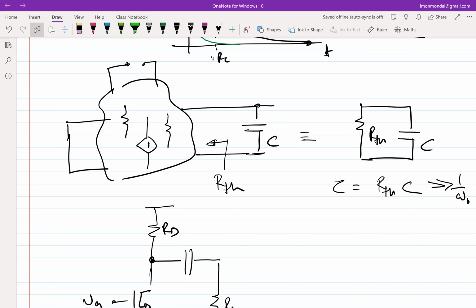This is actually a very fundamental question. Does your time constant depend on the type of source that you have applied, or is it a property of the network? It's a property of the network, right? From that, now the question is, from that property of the network, can I infer certain other things about the network? So if you agree that it's a property of the network, then what type of input I have applied shouldn't matter.